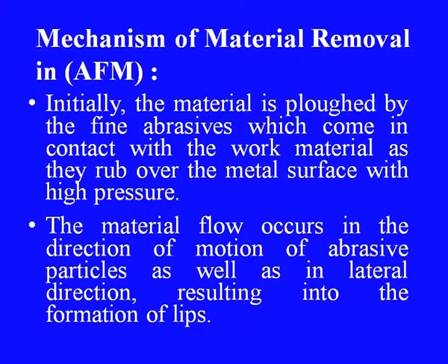The material is initially fluffed by fine abrasives which come in contact with the work material as they rub over the metal surface with high pressure. The material flow occurs in the direction of motion of abrasive particles as well as in the lateral direction. This results in the formation of lips.